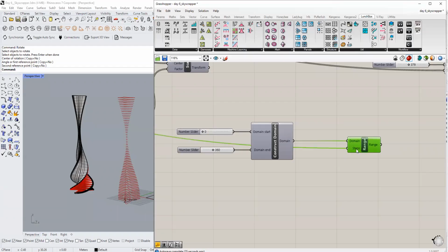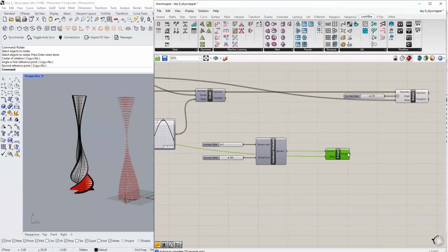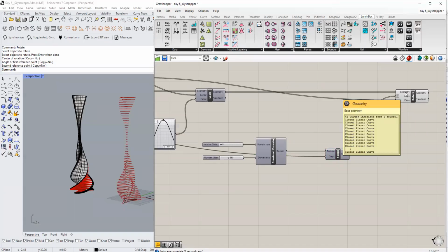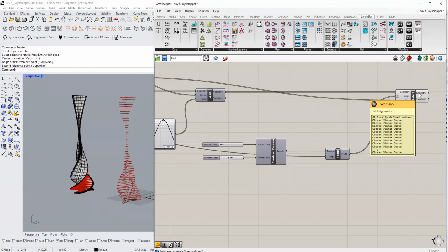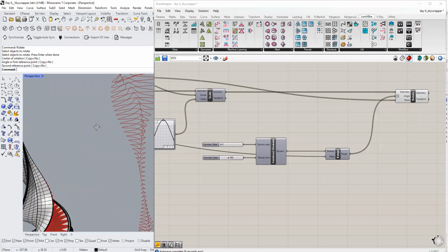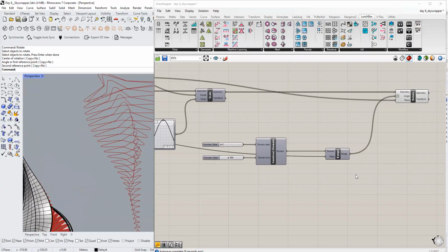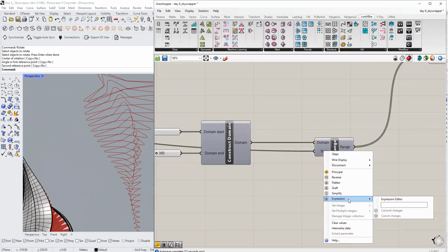And again, don't forget to change the expression, because if you do, and you connect it, there are 61 flow plates, but after rotating it becomes 62. And if I zoom in, I would see the last flow plate overlapping. So do not forget to change the expression. Make sure you definitely do it without fail.